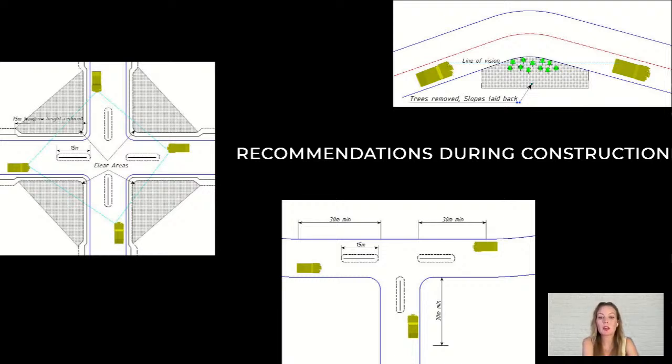This helps them clearly see the area they need to navigate and avoid drifting into the oncoming lane. In summary, ensuring good visibility, giving drivers a clear sense of road dimensions, and avoiding the intersection of more than two roads at one point are crucial for safe road design.